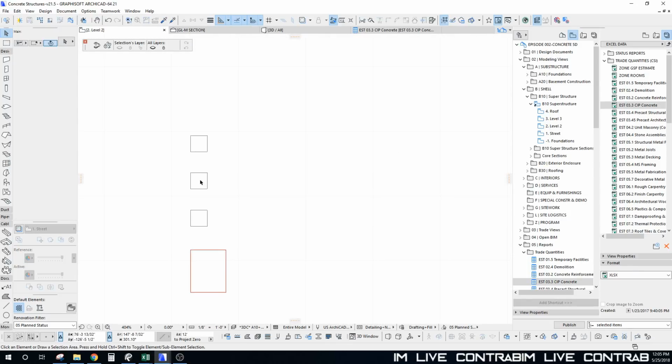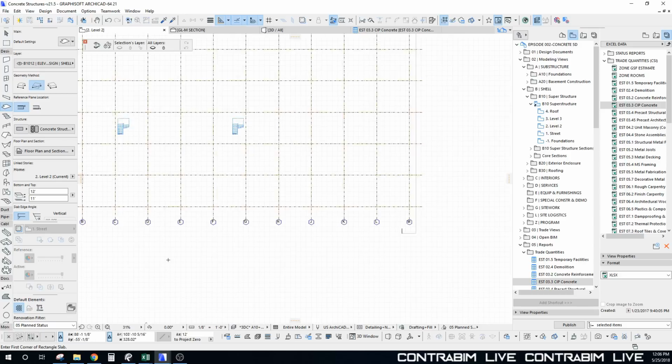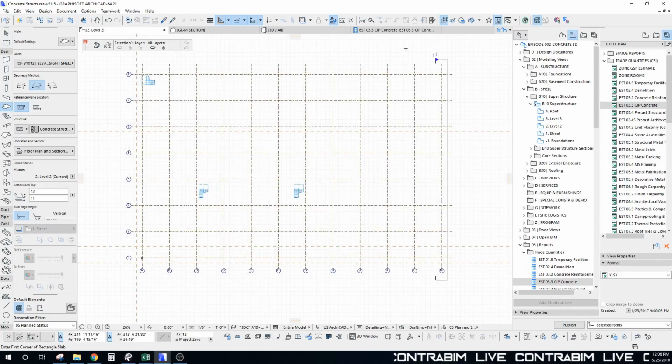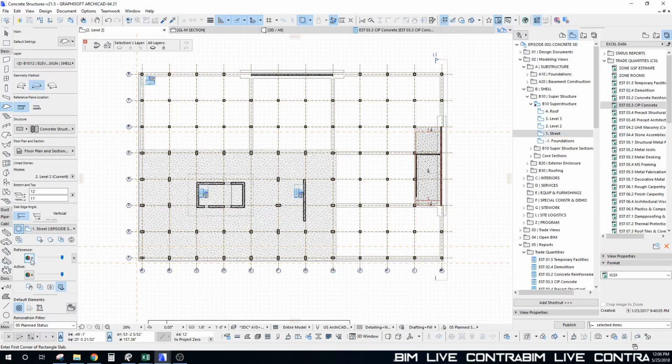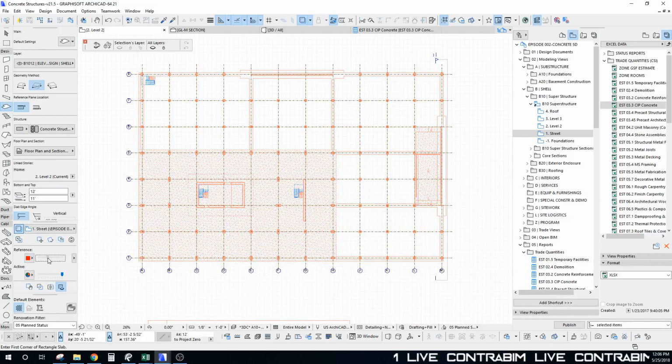And okay, so down here I do have a few elements. A 12-inch deck, if I hover over, an 8-inch, and a 6-inch. So what I'm going to do is pick up the parameter for that 12-inch deck. We'll make a pretty thick structural slab in this case, and I'm going to turn on my level 1 superstructure just as a reference, so that I can see exactly what it is that I'm tracing over. And make this red. We can fade it out a little bit.